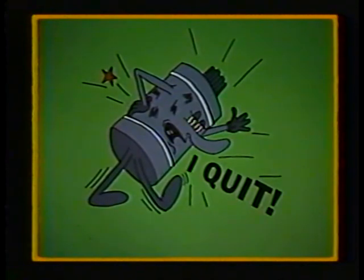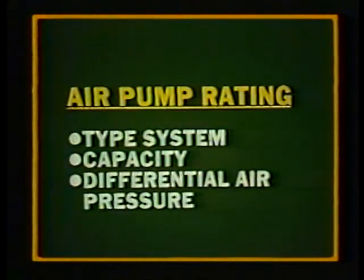Often, a pump will fail because it has been overloaded or overworked, rather than through any fault of the pump itself. For this reason, air pumps are rated according to their capacity and differential pressure. No pump should ever be installed in a pneumatic system whose requirements exceed the limits of the pump.